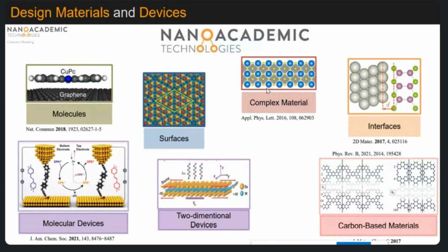Any combination of two or more materials can be created with multiple repetitions in the x direction, y direction, z direction, whatever direction you want to repeat particular single or multiple atoms. The repetitions can be done, including movement at particular angles. So you can create that kind of complex structure, even heterostructures.